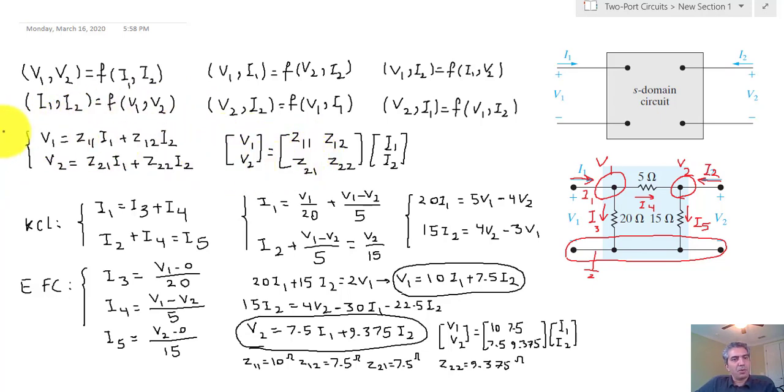As you may imagine, this was called the impedance matrix. If you write it in this form, then the matrix is called the admittance matrix. And then you're going to have y11, y12, y21, and y22 for an obvious reason, because at that point, your voltage gets multiplied by one of these values, and it gives you a current, which means that the unit for those values is 1 over ohm, or mho, and therefore you're looking at the admittance of the circuit.